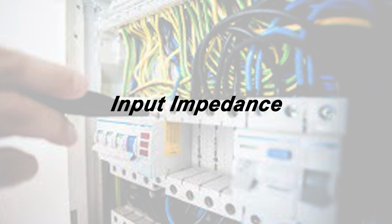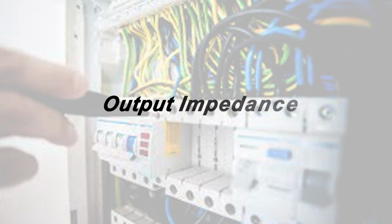Input impedance: calculate the input impedance of the differential amplifier. Input impedance represents the impedance seen by the AC signal source at the input terminal. The input impedance is typically high, making the amplifier compatible with various signal sources. Output impedance: determine the output impedance of the amplifier. Output impedance represents the impedance at the output terminal. A low output impedance allows the amplifier to drive subsequent stages or loads effectively.